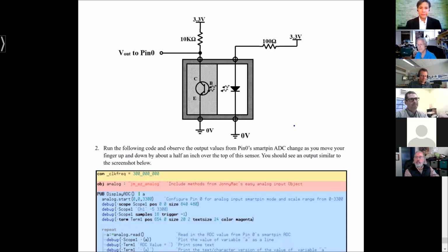Cool. Yeah, that'd be interesting to incorporate into the book. That's a neat idea. And is he using a comparator smart pin too? Yeah, he was using the low-level configuration of an 8-bit level compared to the pin. So it's basically just using 2 pins. So one smart pin in DAC. Just 1 pin, one pin in a level comparator. Yes. If you look at the mode chart for the low-level pins, the last couple are where you compare an incoming pin to an internal 8-bit DAC.